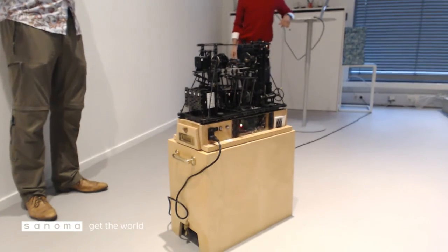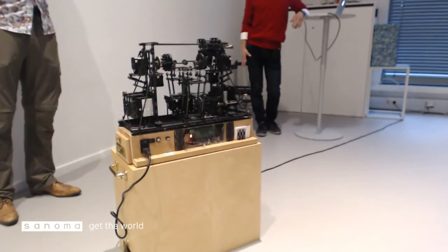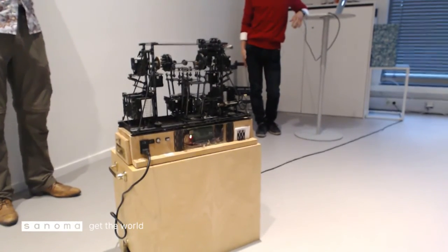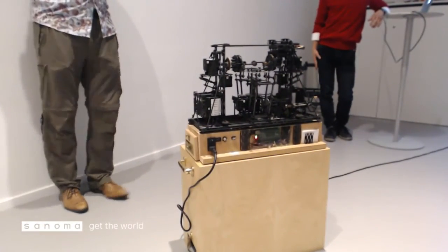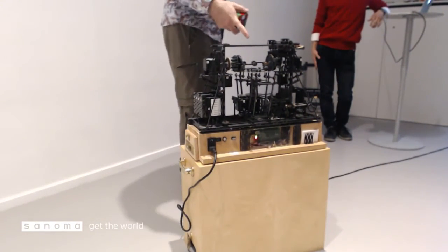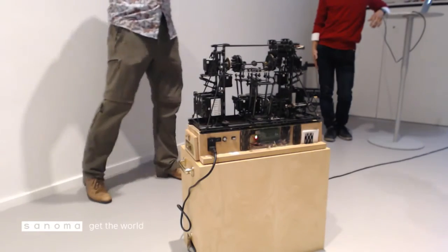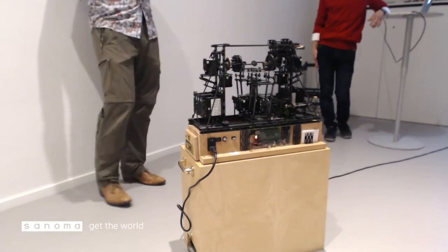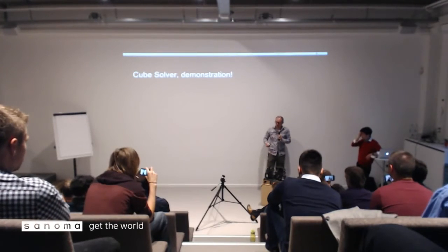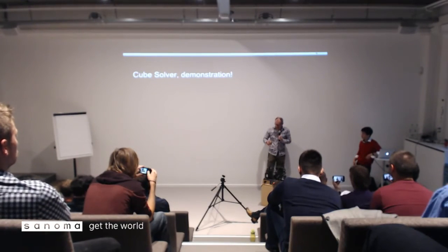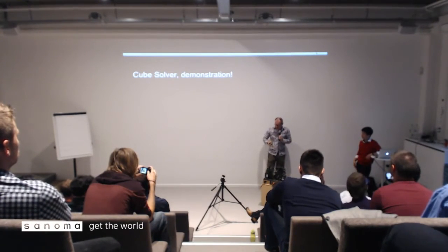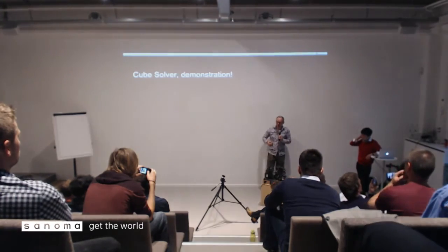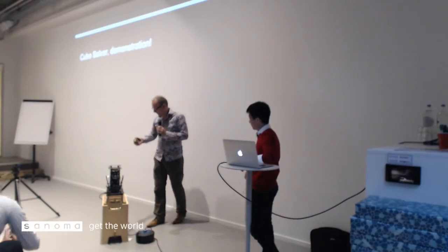Sometimes it occurred that the cube was a fraction lower than it should be. But I placed two black plates on the upper side of the positioning table. And then that problem was solved as well. So that was actually one of the easiest things over the time.